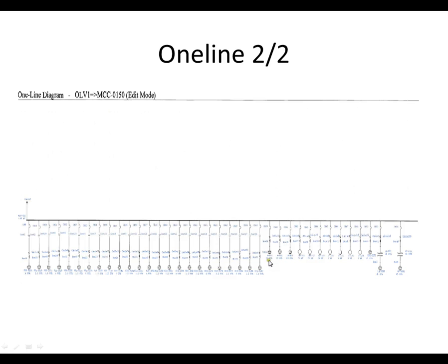There's a couple ancillary loads here. You've got 3 tank heaters. You've got a crane inside the compressor building. You've got 2 instrument air compressors. You've got your 4 exhaust fans. And then you have an uninterruptible power supply, UPS. And then you've got a 120 volt lighting panel and a 120 volt heat trace panel, which basically just keeps the pipes warm in the harsh cold conditions of North Dakota.